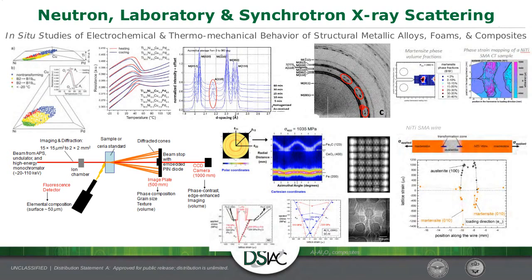We can also do in situ fracture mechanics, looking at phase distribution, and also how the stress in the individual phases looks, and orientations. I mentioned the different techniques. We can put our sample in, do fluorescence, do X-ray diffraction, both wide angle and small angle, and we can also do imaging, so you can couple all that together. For example, if I want to look at damage evolution in a composite or in a structure that has phases with a density difference, we can look at how the material becomes damaged and how those two phases interact, the load partitioning between the phases. That may be useful.